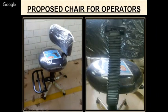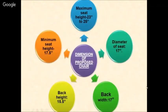So the proposed chair was this one, which they found from the market, and this is the footrest where they can keep their foot. And again, this is adjustable. Chair height is adjustable, and the dimensions of the chairs which they recommend: maximum seat height is 23 to 25 inches. Minimum seat height is 17.5 inches. You can adjust between this minimum and maximum seat height. Diameter of seat is 17 inches, with a back height and back width as shown.